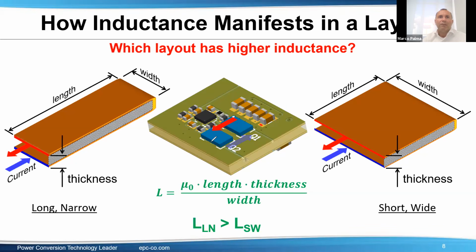Okay. You have two choices. If you spend a little bit more on the PCB, then you can put the via directly on the pad. And what you have to do is ask your manufacturer to do what is called via in pad plated over. That means if this is the pad, the via is inside, and then they will fill it completely and plate it over, so it will basically disappear. You don't see it. It's there, but you don't see it, and that's perfect coplanarity. This costs you more, but it gives you the best performance.